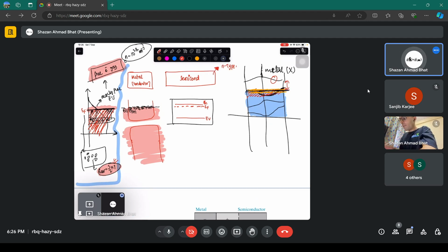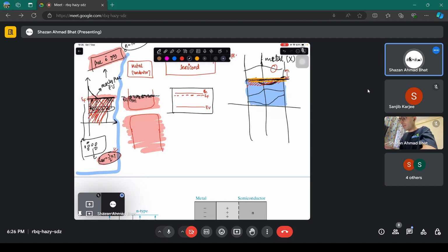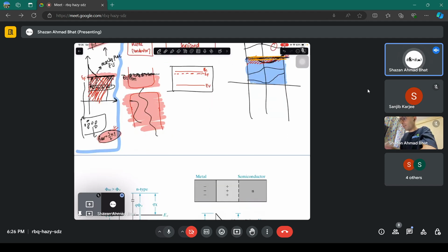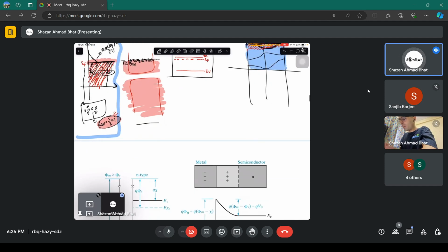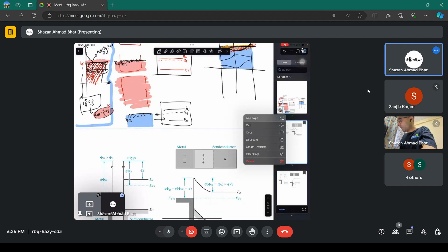So now we have many electrons present here near the Fermi level. Okay, so what is going to happen when we connect these two? Now we don't exactly show these particular regions in a metal. We just show a single Fermi level, and we consider that up to this Fermi level, electrons are totally filled. A huge number of electrons. And when you bring in the semiconducting system, which has a conduction band here, Fermi level here, valence band here, close to this, you make a contact. And what happens when you make a contact? That's what we are going to see at page.